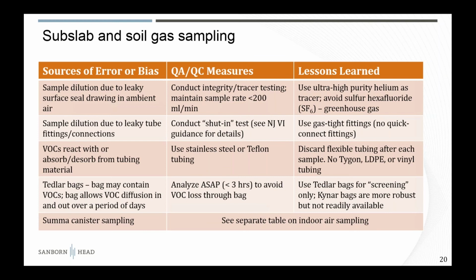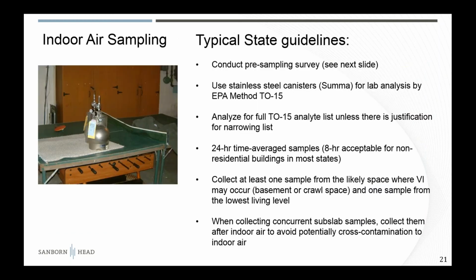And then for SUMA canisters, this is how you would normally collect a subslab sample or an exterior soil gas sample. There's a whole other table on that we'll get to shortly. So moving on to indoor air sampling, these are the typical state guidelines, pretty much things that are well recognized that should be considered in conducting an indoor air sampling program. It kind of starts with a pre-sampling survey, which we'll talk about on the next slide.